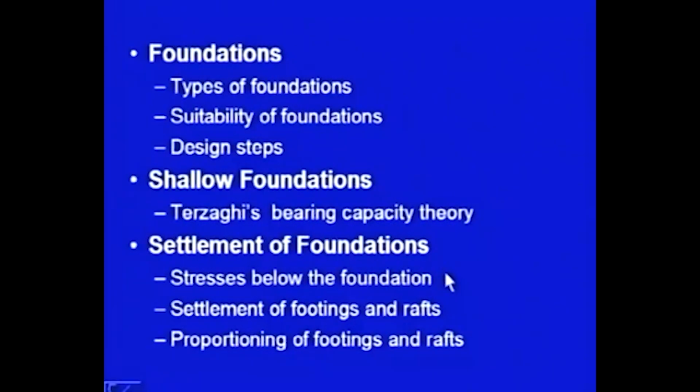For that purpose, we shall need the stresses, how the distribution of the stresses takes place below the foundations. Then we shall discuss in detail how to calculate the settlement of footings and rafts, and then proportioning. Once all these things are available, then for a particular type of loading, how to proportion the footing, how to proportion the rafts, this we will be discussing.